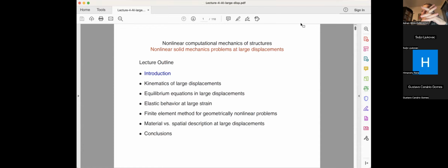Then a second difficulty is that in the small deformation theory, we have shown that in the 3D case, the strain measure is simply the symmetric part of the displacement gradient, and the complementary skew-symmetric part is a rotation. Both of these are infinitesimal, so often we call this infinitesimal strain if there's no rotation, and both of them could be represented as a linear operator.